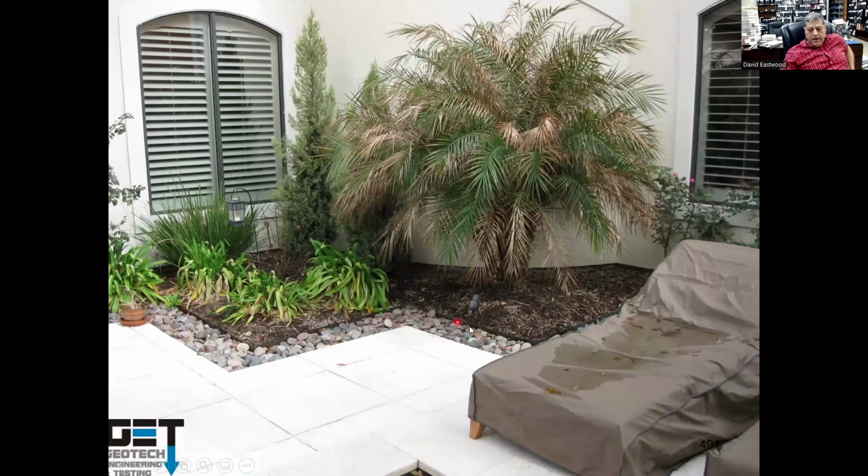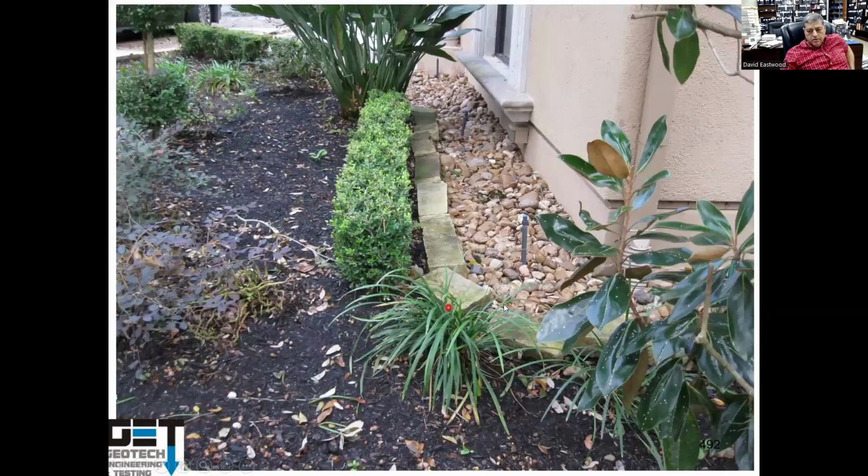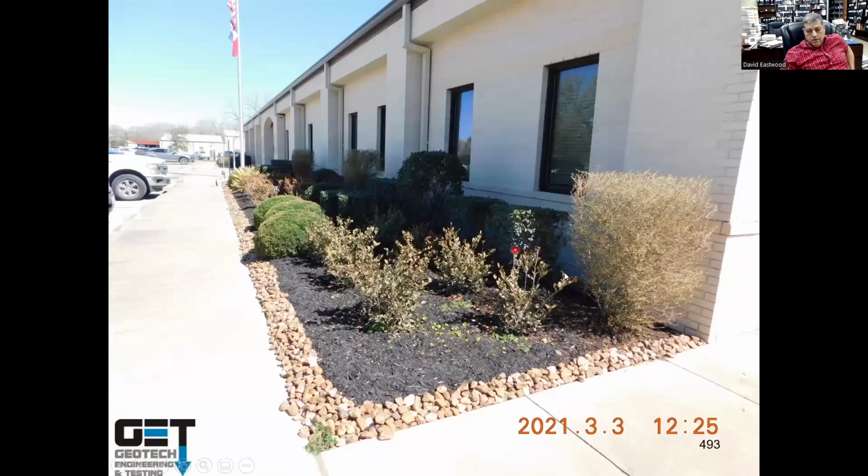Bed liners next to the house in Westview, the gravel. It drains, water holds in here, causes movement. Sprinkler system, bed liners next to the house in Friendswood. This is Brazoria County offices out there in Brazos, Texas. You can see topsoil here, and you got gravel here, holds the water next to the highly expansive soils underneath the building.